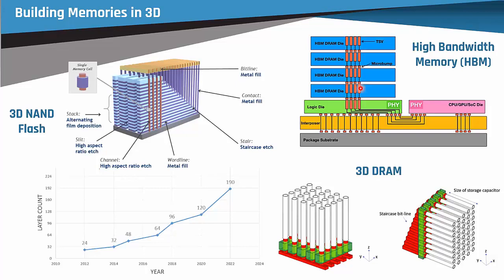It's similar to whatever Foveros and stuff is. They're working on something called 3D RAM. As far as I know, there are no products yet, where with DRAM, you have this stacked or trenched capacitor. So this is a stacked capacitor. This white thing is the capacitor that goes way up to get this high capacitance you need in the DRAM cell that sits on top of the transistor.